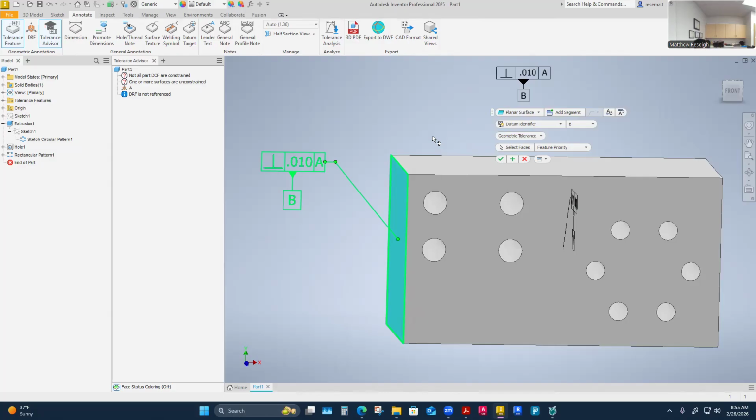To me, when I apply welding symbols and GD&T on the drawing, they don't feel adaptive or like smart dimensions. They're just kind of static. And this one helps me establish it maybe more correctly. I don't know. This is exactly what I want. This is what I feel like is missing on my actual drawing. It should say datum A. I'm holding perpendicularity at 10 thousandths from datum A.